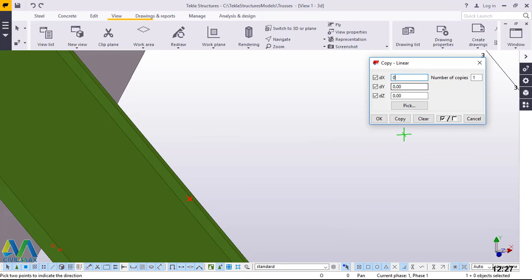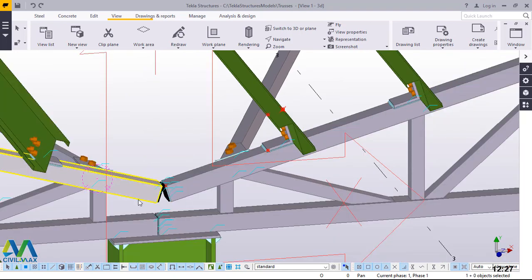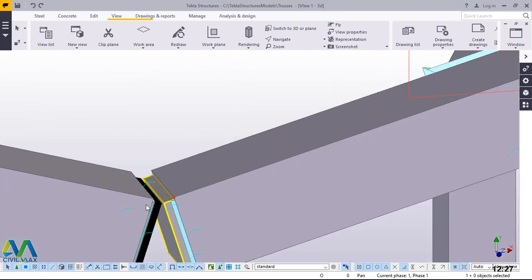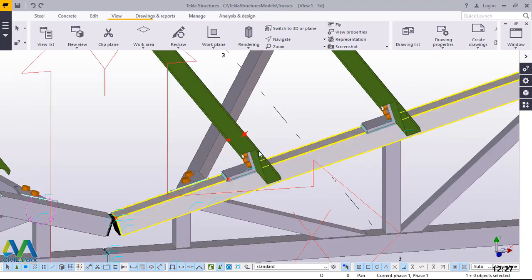First of all, we change the x-axis to 0, then come to y-axis, we change this to 3, but we have prefixed this dimension with a negative sign right here. We'll just click on that and feed a negative sign. We'll click OK and accept that by clicking an OK button. Now we are on the right track, and what we're going to do next is very simple. It's just to mirror this to the other end.